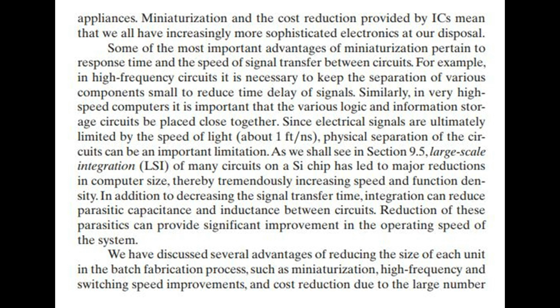As we shall see in section 9.5, large-scale integration, LSI, of many circuits on a silicon chip has led to major reductions in computer size, thereby tremendously increasing speed and function density. In addition to decreasing the signal transfer time, integration can reduce parasitic capacitance and inductance between circuits. Reduction of these parasitics can provide significant improvement in the operating speed of the system.